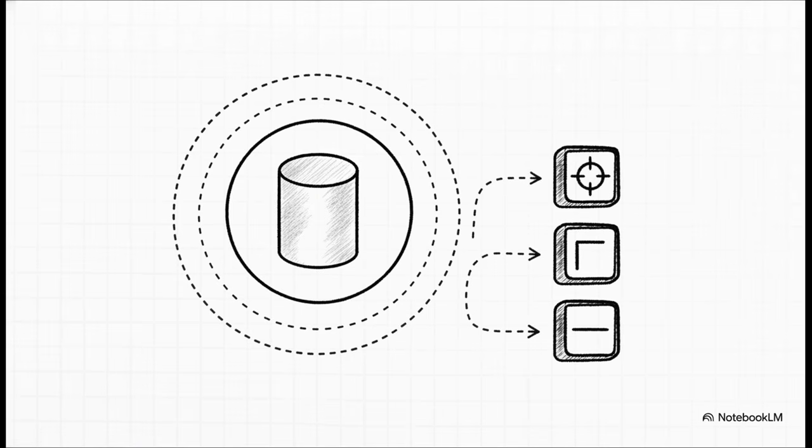For the primary datum, the outer boundary is just your maximum material condition plus the straightness tolerance. Simple enough. But check out the secondary datum. Now you're taking MMC plus perpendicularity plus straightness. And by the tertiary datum, you're combining MMC, position tolerance, and straightness to form this massive outer boundary. These tolerances literally stack up on top of each other before you even try to mate 2 separate parts together.